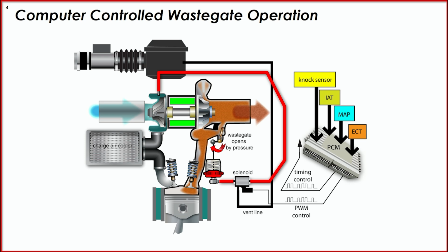Now, for most engines, this would create an excessive amount of boost or airflow and destroy a lot of parts. We definitely don't want that. So, to control boost and engine power, these turbo systems are going to rely on wastegates, which are mounted before the turbine housing or inside of it, in the case of say an internally gated turbo, and act as a controlled bypass for a percentage of exhaust gas to regulate turbine speed and boost. And of course, there are various design differences in wastegates. There's a couple different types out there, but if we think about it in the most simplistic terms, every wastegate is going to feature an inlet and an outlet port through which the exhaust gas can enter. It's got a valve that regulates the flow of exhaust gas through the inlet port.